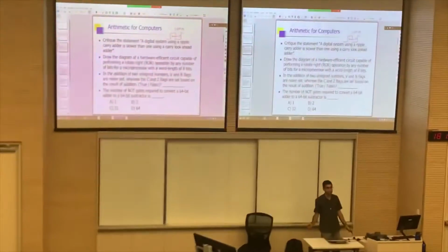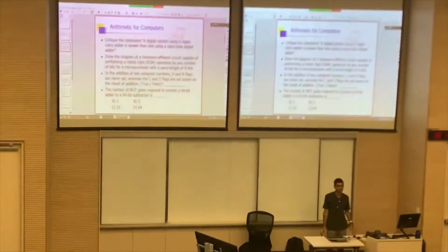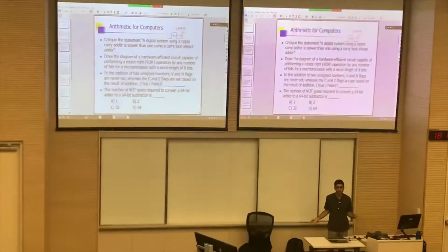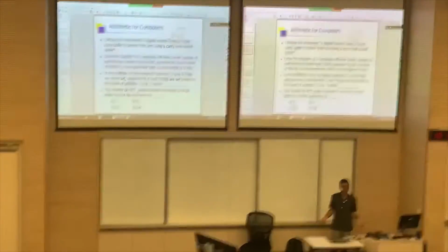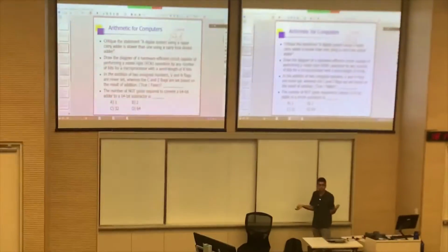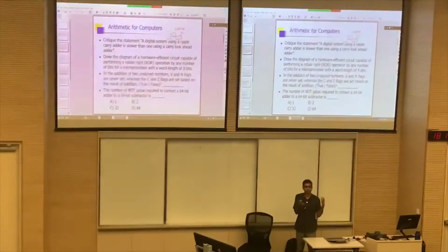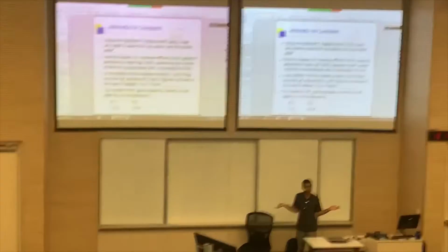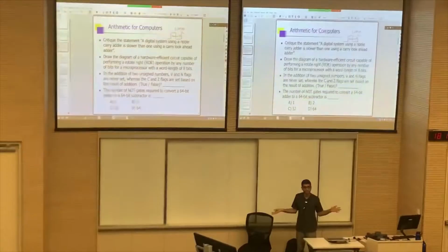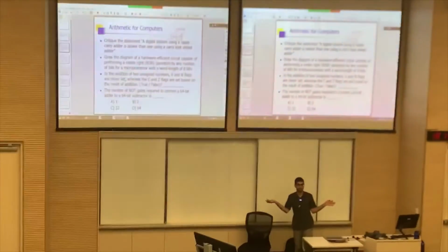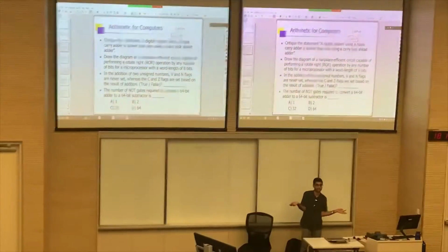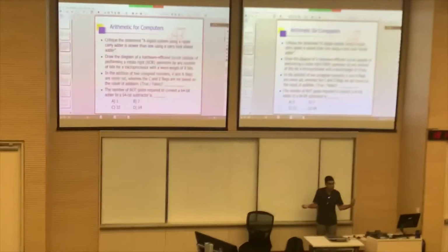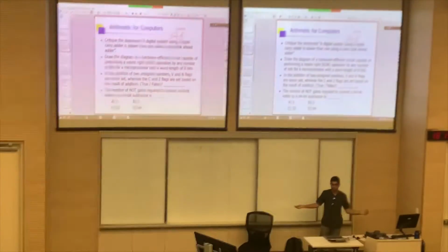Okay, it also depends on whether this adder is in the critical path or not. No point in trying to improve something which is not the bottleneck. Right? If there is some other circuit which is even worse than your adder, no point in trying to throw in money or extra hardware to make your adder faster when it's not the bottleneck anyway. So if your adder is not in the critical path, don't bother trying to make it high performance, because you won't get anything out of it other than perhaps the satisfaction that your adder is fast. It doesn't translate to an overall improvement in system performance.